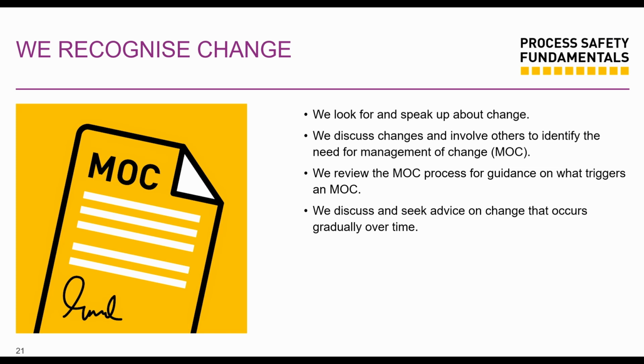You're adding parts and parts and parts to it, and you're adding valves, you're adding vessels, you're adding drains, you're adding pipe racks. Stuff has changed. Are you capturing each change in an MOC? We're supposed to have an MOC process in place to capture and risk assess every change that we're doing, and see what could trigger unhealthy or unsafe conditions. So we are supposed to discuss these changes, and involve various disciplines that could have different views from us, to look into those changes.